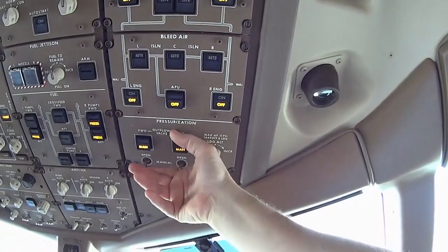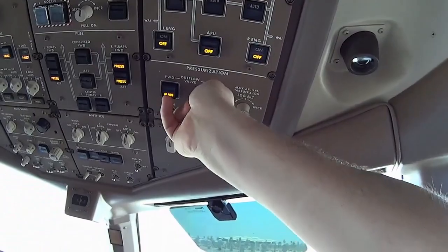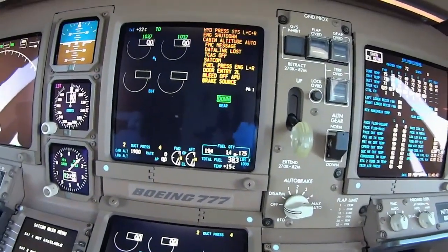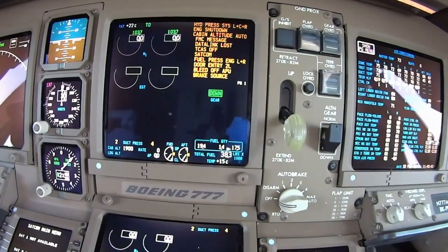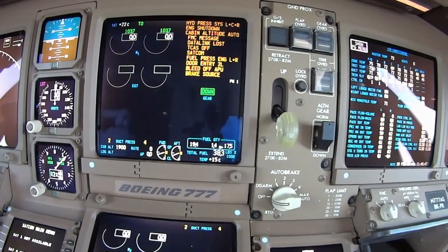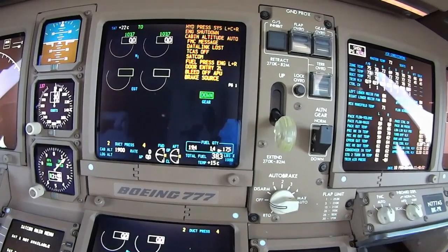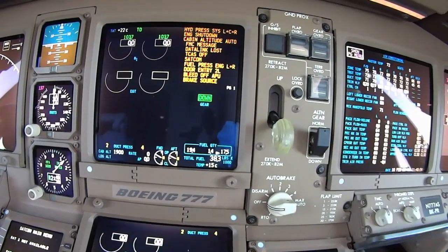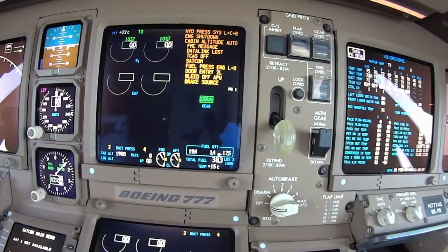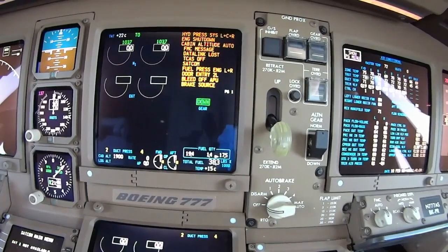Actually, let's open these. These are the outflow valves that we saw on the outside that are closed. They're in manual position right now. That's them starting to move, in the middle where it says forward and aft, OPCL. M stands for manual mode, and I'm moving them to the open position. Now when we get in flight, those will automatically modulate to control the pressurization inside the cabin. If we get too high a pressure, they open up. If we get too low a pressure, they...